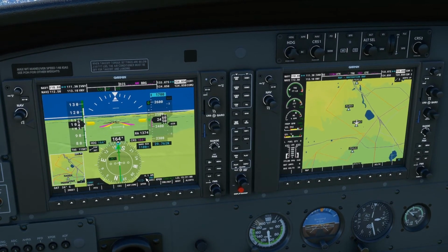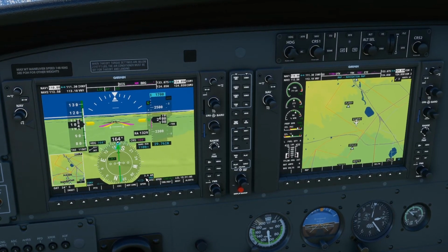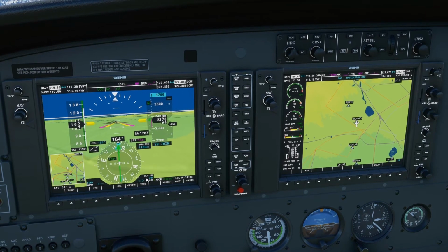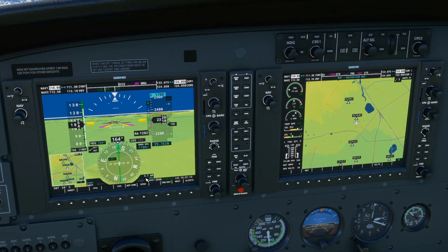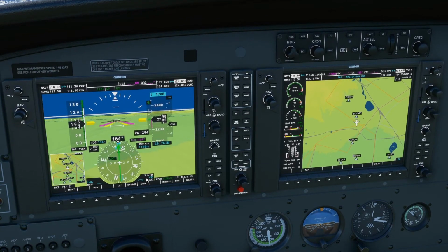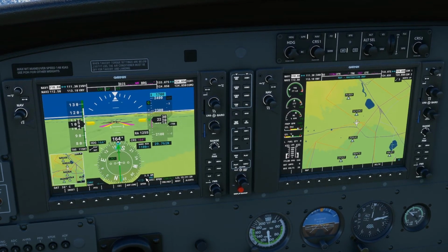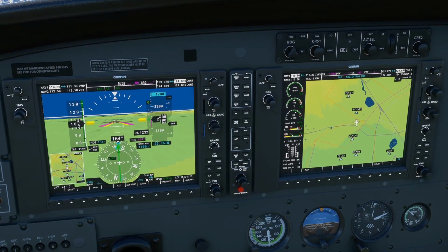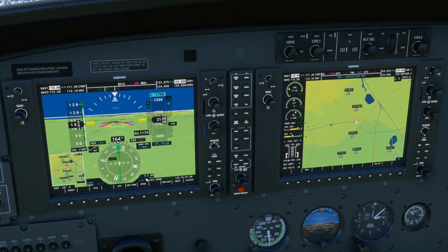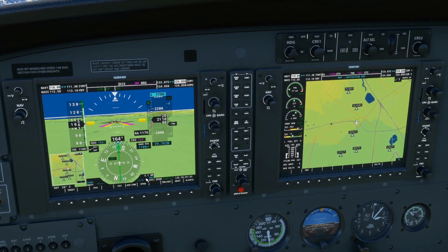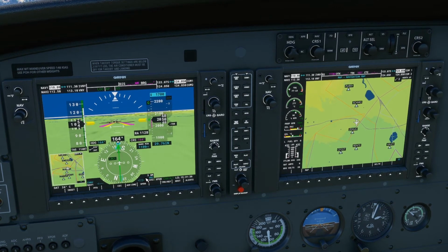So 1.5, in case of go around, we will go manual, so autopilot disconnect, go around thrust, climb altitude, flaps 20, climb to 1,700, and at 1.5 DME we will turn slightly left, heading 152 to intercept the 152 radial, so we will change to the VOR 2. And in there we should have 152 and follow that initially, and then we will review the rest.